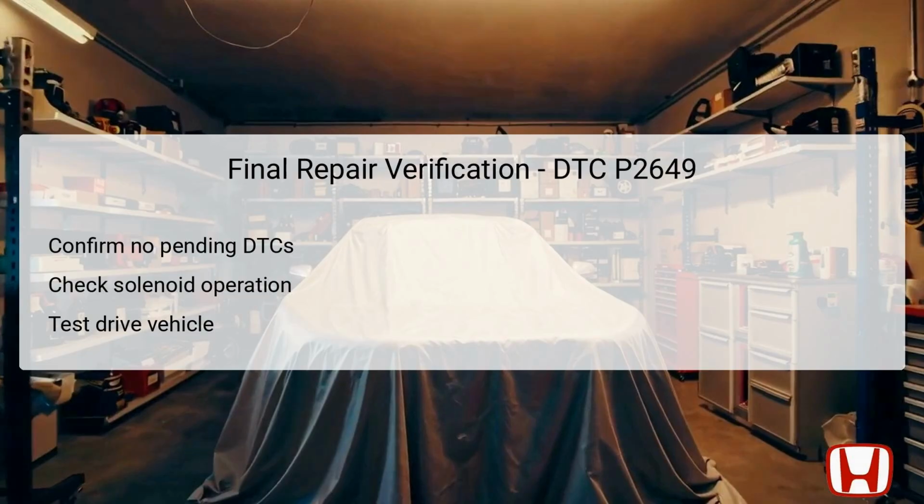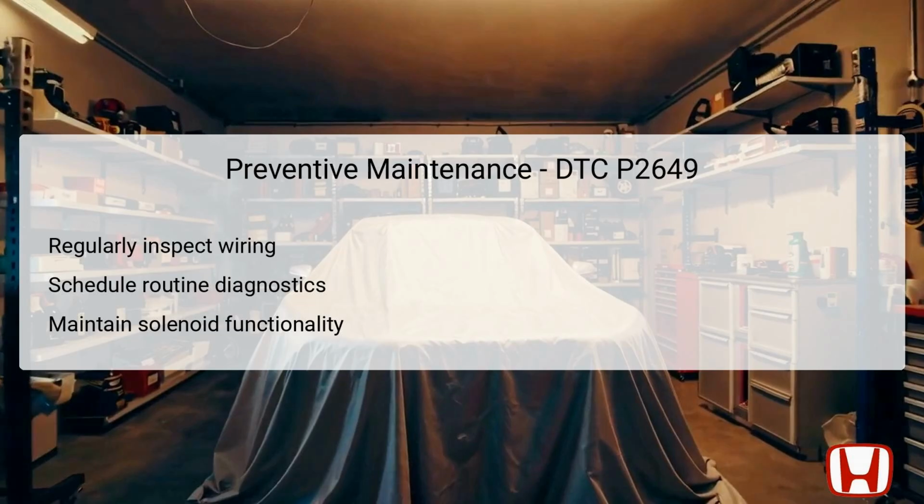This verification stage holds significant value, as it not only checks the effectiveness of the repair, but also reassures the driver of the vehicle's reliability. Preventive maintenance plays a key role in minimizing the chances of encountering issues like DTC P2649 in the future. Regularly inspecting wiring components and connections associated with the rocker arm oil control solenoid ensures any wear and tear are identified sooner rather than later.